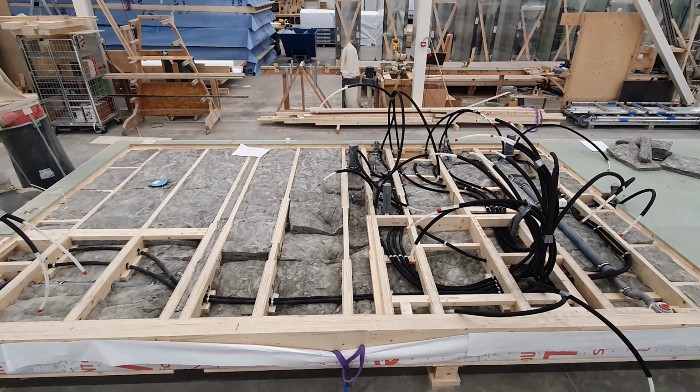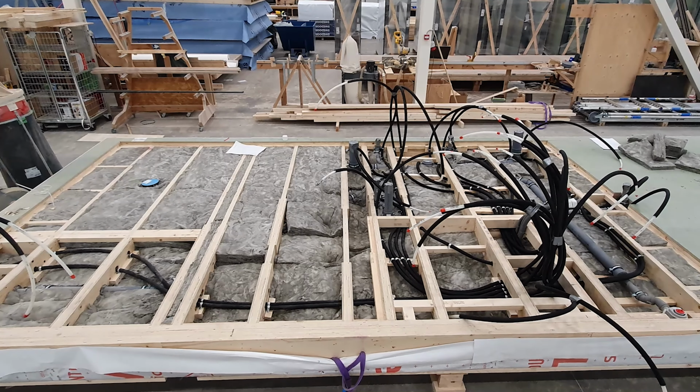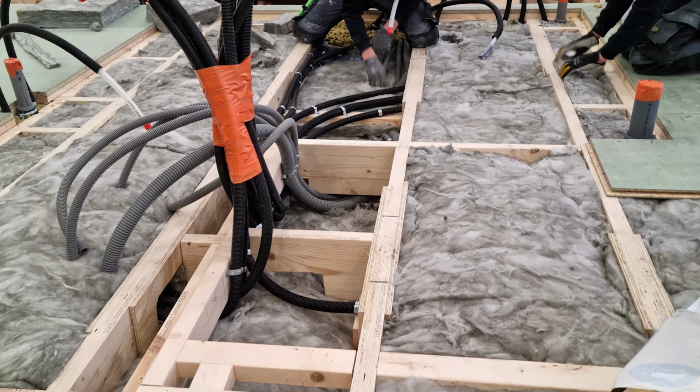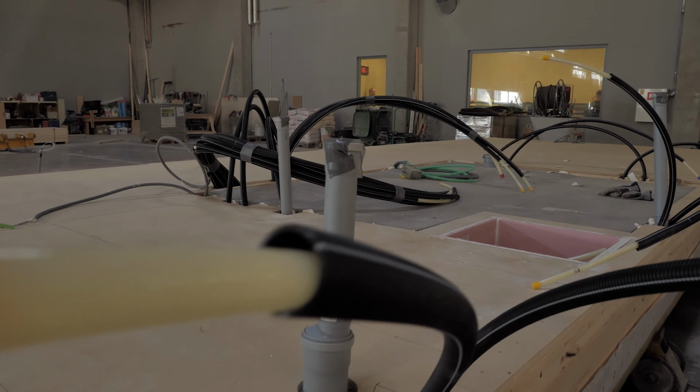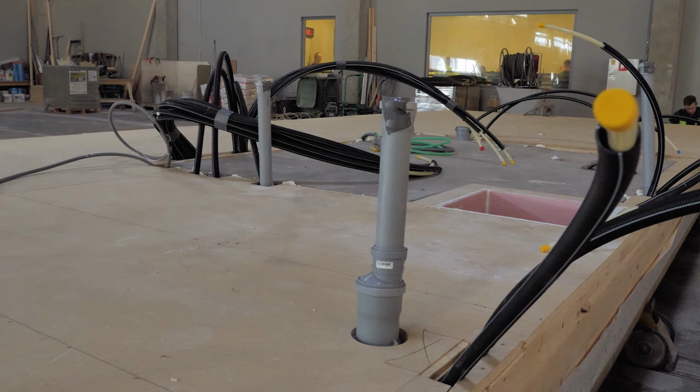When installing plumbing, it is essential to follow the fixing solutions developed by the company. These should ensure that the plumbing is securely fixed at the prescribed intervals. Water pipes must be installed and secured in such a way that it's possible to replace the pipes inside the casing if needed later. If there are pipe penetrations in the floorboard, then the board needs to be milled for an opening with a diameter approximately 20 millimeters larger than the pipe or pipe bundle. The pipe penetrations are later sealed with the designated sealing compound.